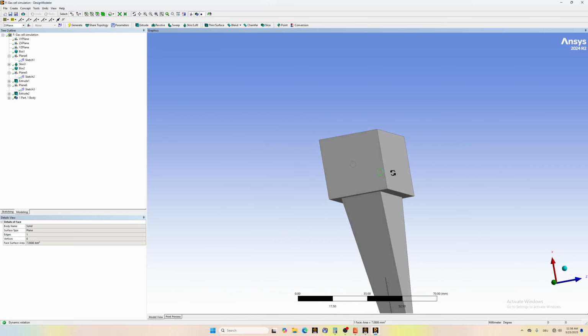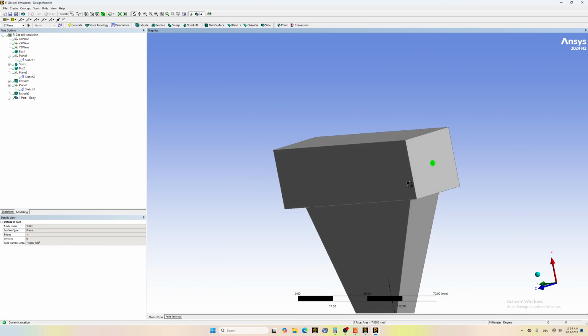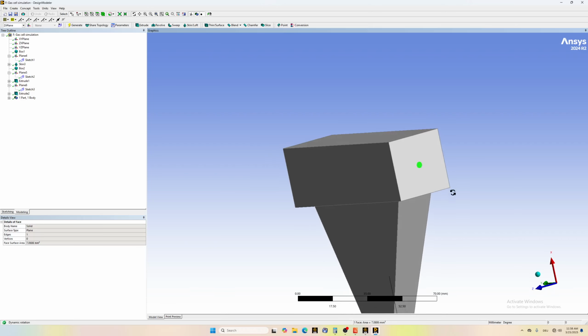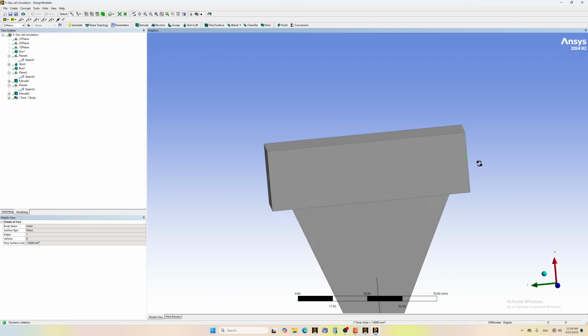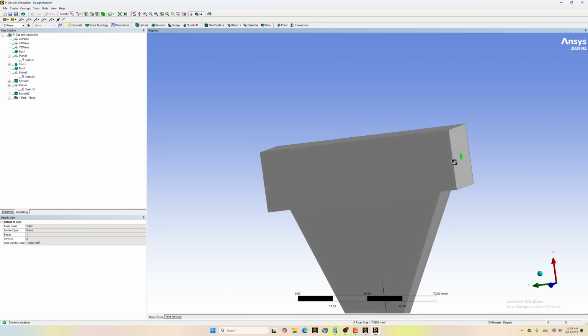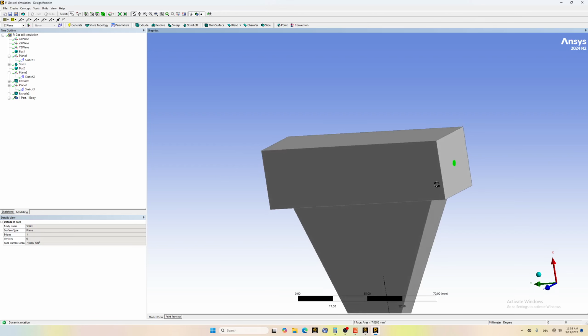Of course, if you want to see the density profile, you need to define a region outside this part. I will not do it now because I want to save time. So you can modify it in any way you want. As long as you know these steps, how to define these small parts in the outlets using the imprint phase, then you are good to go.